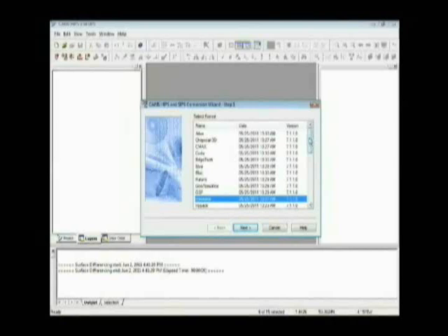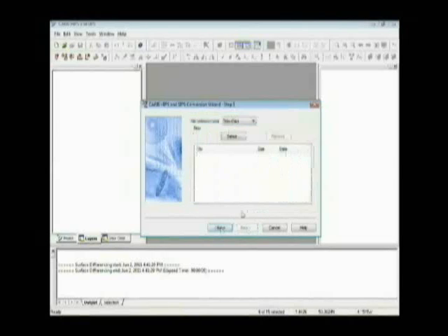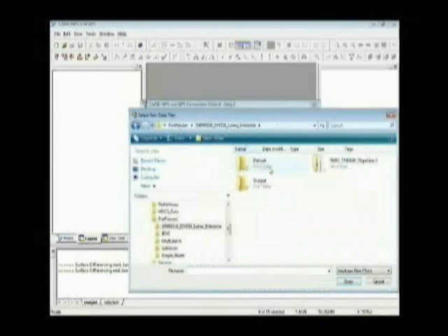Now, then there's lots of other formats. So for all those newbies out there that haven't used HIPS and SIPS, you can see it starts at Atlas, and it goes down. We can see we have HIPAC, LADS, we have Reson, we have Shoals, Simrad, SWATH Plus, and going down to XTF. Once we have Hawkeye selected, we can select Next, and then go to step 2 where we're going to select our raw data.